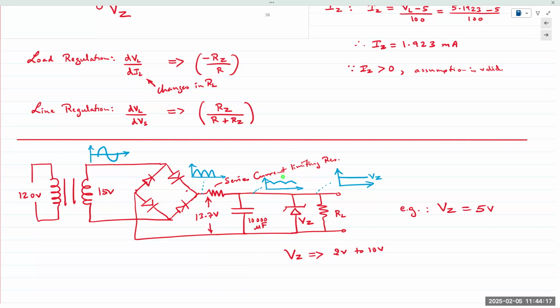And then before the capacitor, this peak value can be anything, maybe like 12 volts or larger. And this here should be about 25 volts peak to peak, the output of the transformer. Probably even bigger than that.